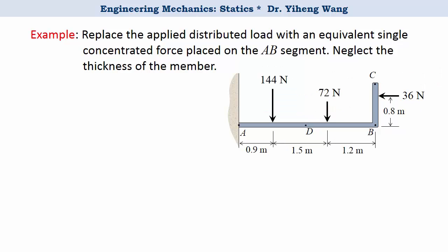And now the distributed loads have been replaced by their respective concentrated forces. Their locations have been specified. We can easily determine the total resultant force along the x direction, along the y direction, and also the total moment calculated about point A.